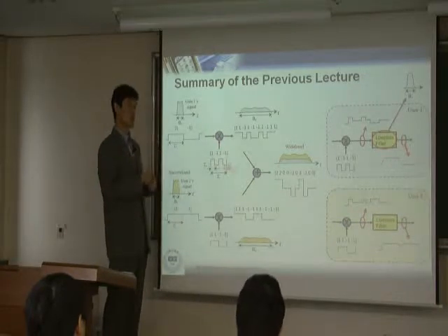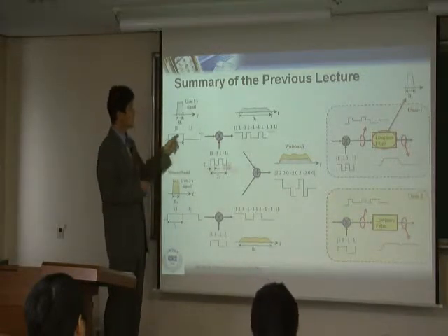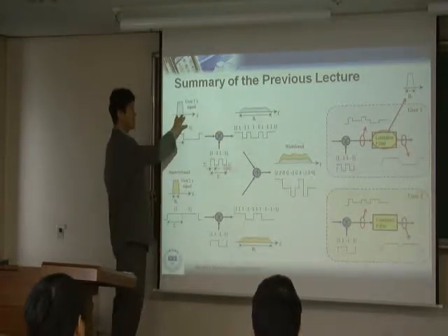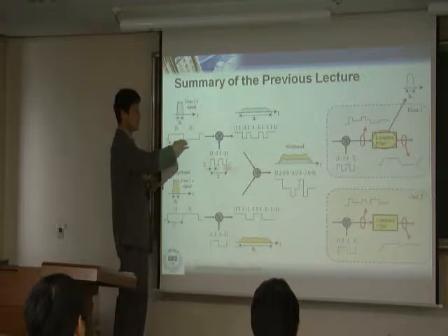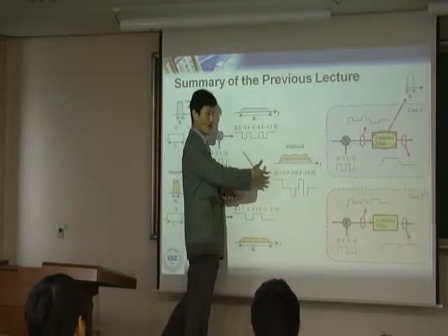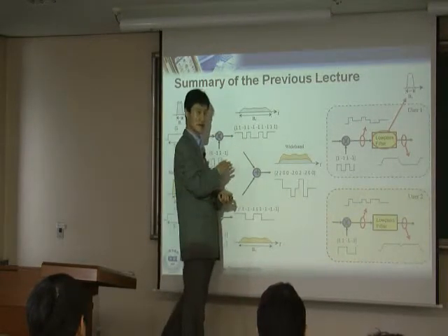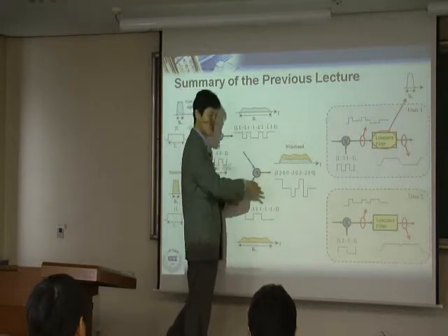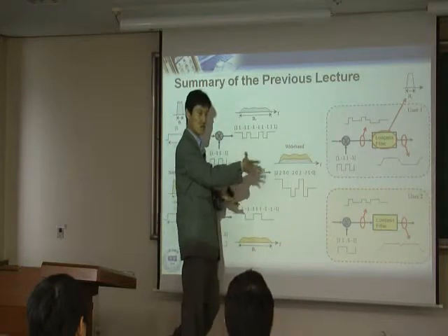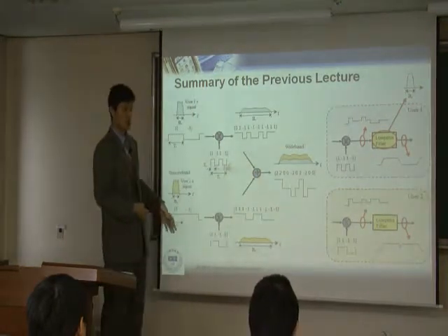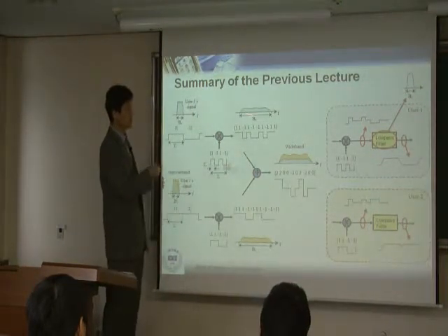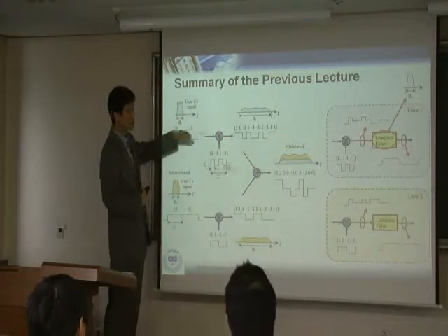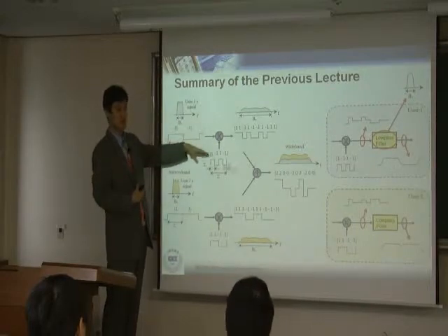However, what is even more challenging is that we are talking about a fading channel, right? So this guy transmits a certain power. That power now experiences fading, so that power is not actually consistent. Sometimes this guy's power is received big, sometimes small, okay, because of fading. Same thing for user 2. So therefore, you have to actually change your transmit power based on the fading, considering all these things.